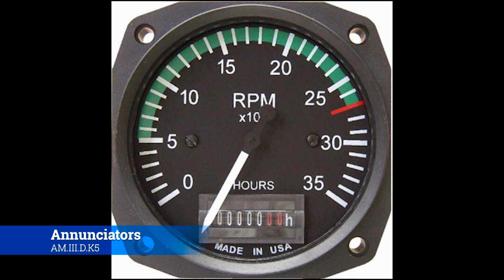This is also a good way to set the performance for the airplane in the traffic pattern. Whenever you make certain turns in the traffic pattern, you might set it to 2,000 RPMs, or 2,300 RPMs, or 1,700 RPMs, or you might pull it to idle, depending on what you're trying to accomplish and where you're at. So this is oftentimes the gauge that the pilot is going to be looking at the most in order to set the RPMs correctly.